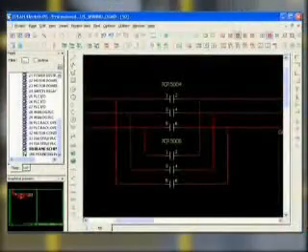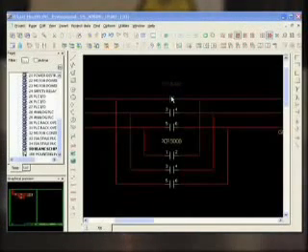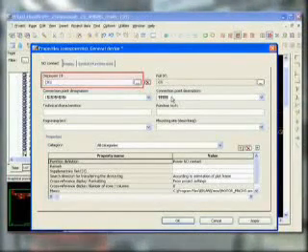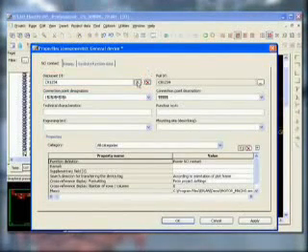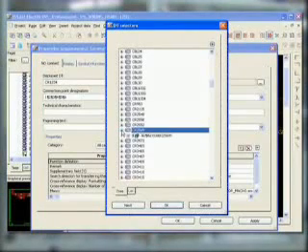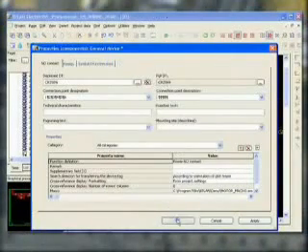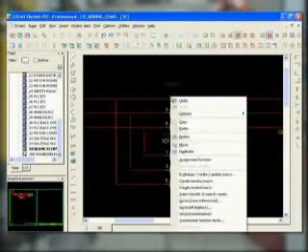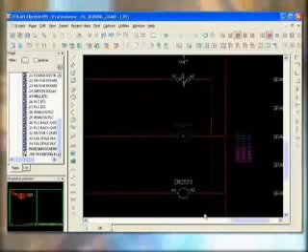Eplan will automatically cross-reference your schematics for you. To cross-reference devices, simply give them the same name. Eplan will take care of the rest. For a coil and contact cross-reference, select a set of contacts and fill in the correct name of the coil they belong to. You can also select from a list. Eplan then links the 2 devices together. To jump directly to the coil, select Go To Counterpiece. The contact image cross-reference is updated automatically next to the coil.